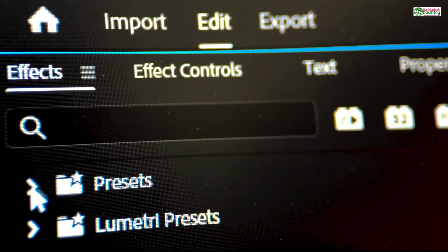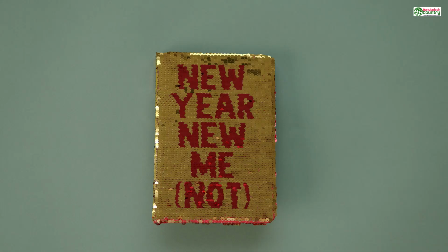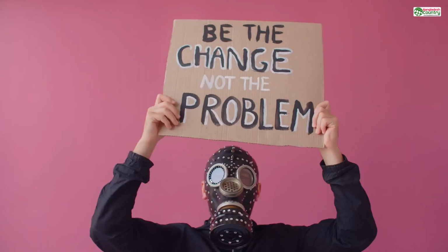Go into those red zones and thicken them up. Maybe you need to add a bit of material to the back of that flowing cape. Maybe you need to make that sword blade just a little less realistic and a little more robust. You make the changes, you run the analysis again, and you keep going until all the red is gone.